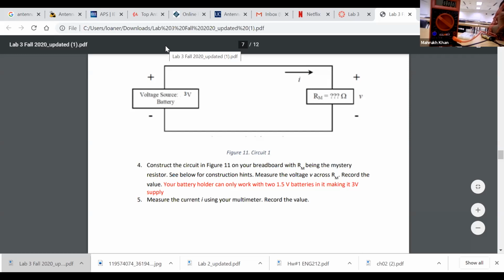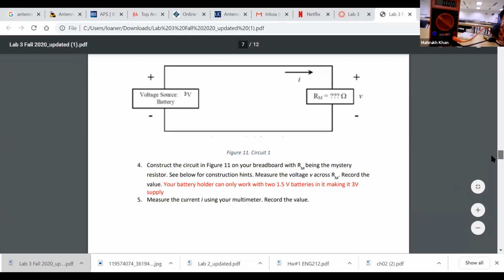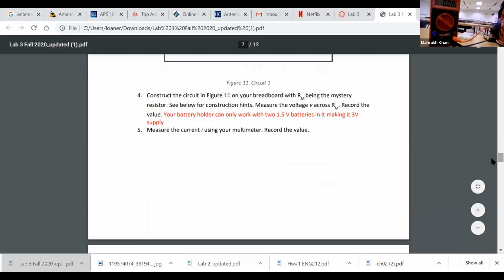Even I am going .98. So the maximum value I will record in the table. You make the table yourself, since it didn't mention the table, across which you may measure. This is the voltage you have recorded, 2.98 in my case, and then you will put the current. For the voltage, I just put my leads across the legs, in parallel with the equipment, or the resistor.